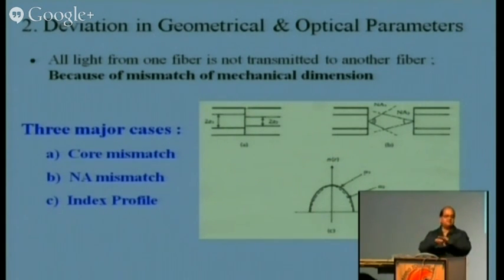Today, you laid your system. Maybe after 10 years or after 15 years, there is a break in the system and you have to make a joint. And technically when you have to make a joint, your fiber will be damaged, maybe by digging or by some other means. So you have to prepare the fiber for the joint. You have to cut the fiber and make the fiber end very smooth, then you will make the joint. In this process, generally maybe 1 meter of fiber is required.